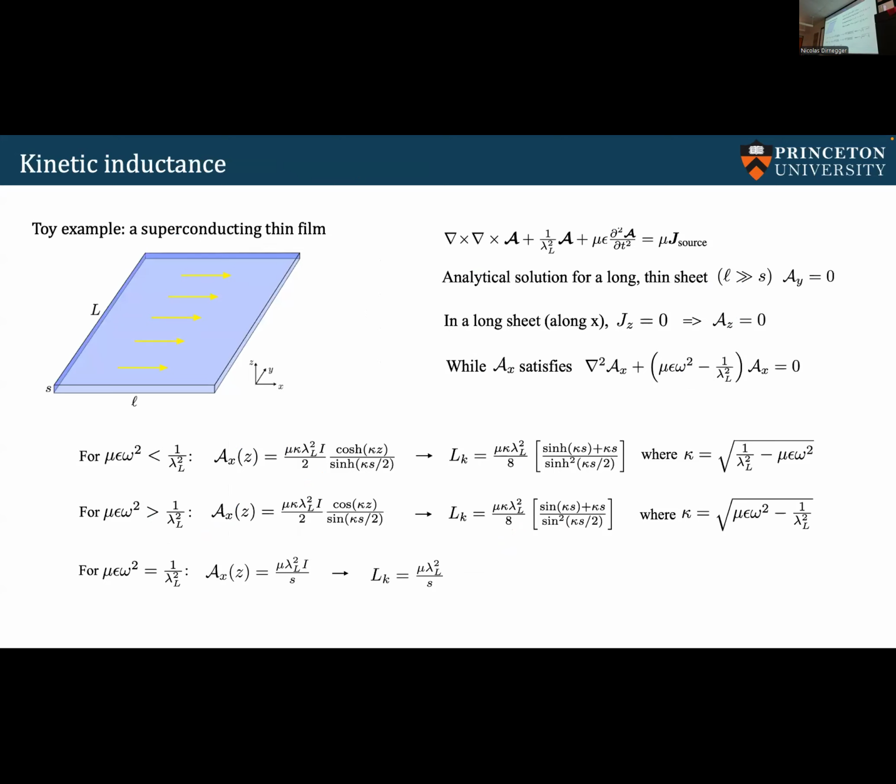And of course, you can compute kinetic inductance, which is the measurement of the inertia of charged carriers in the materials. And kinetic inductance, therefore, is directly related to the kinetic energy of the charged carriers. In the context of superconducting materials, those are the Cooper pairs. And because we have charge density, or the evolution of charge density being encoded into our formulation, you can very easily compute the kinetic energy of all the charge carriers through this framework. And then from there, extract kinetic inductance.